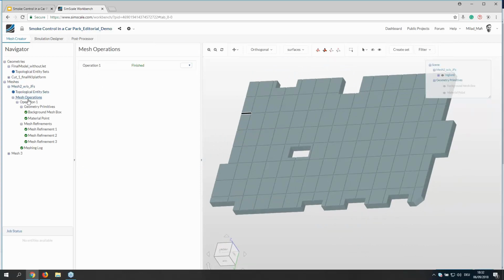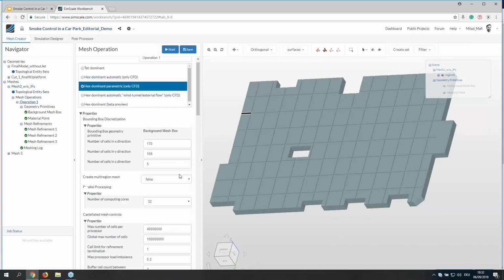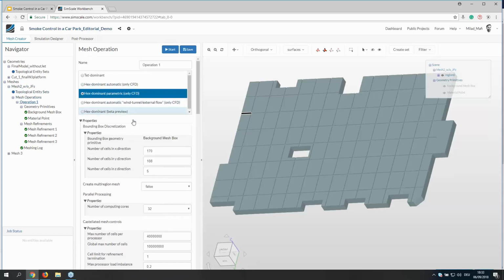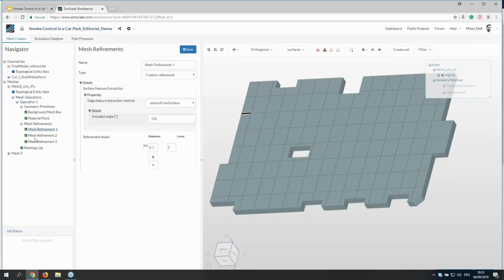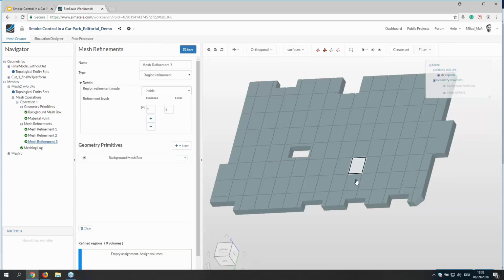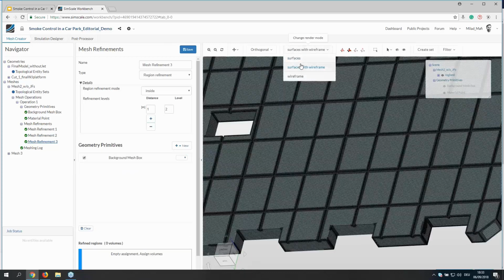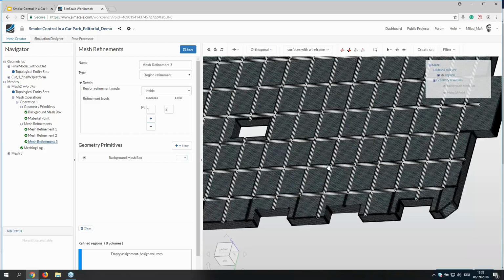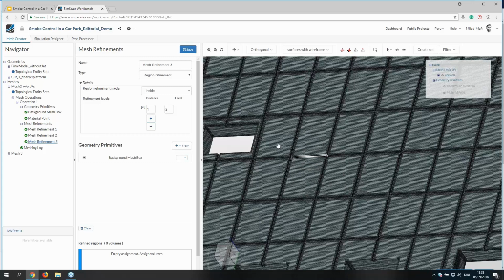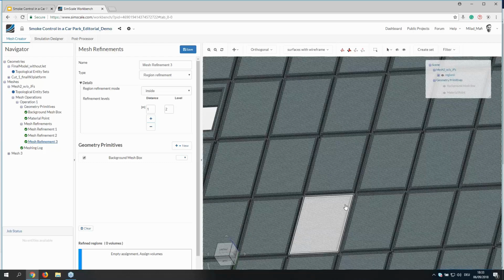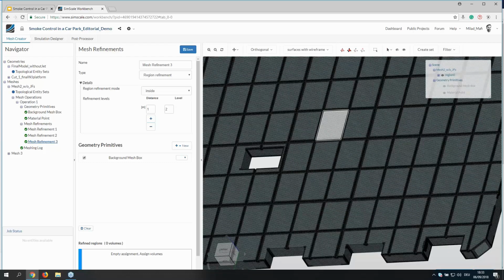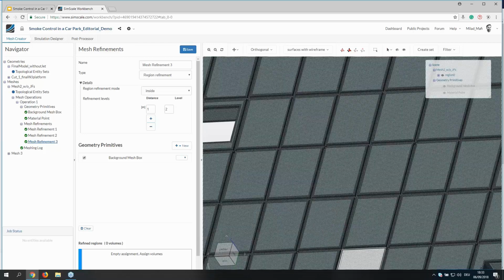I don't want to go too much into detail, but you can choose between different mesh operations we have. We have full automatic mesh operations and half automatic ones, and then you can define different refinements, because the resolution of the cells in the end of the day represents the local resolution of your simulation. So as fine as the cells are, as more precise your simulation in that area. Therefore you make the mesh, for example, smaller in the near of obstruction objects and far away from the flow, or in the near of the wall you make it also a little bit finer to resolve wall effects.